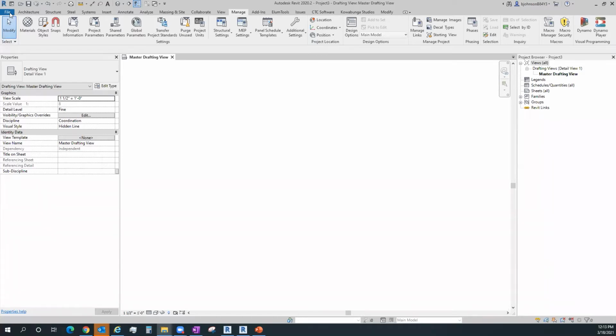Somebody's just asking why explode the hatch patterns and M text. You can change them in transfer in Revit. I'll be able to show that in just a minute. If I have like the earth hatch pattern, I would leave that intact and just swap that material or that pattern, fill pattern, with the one in Revit.